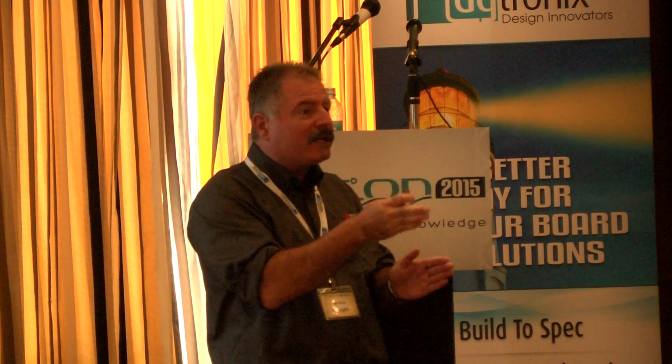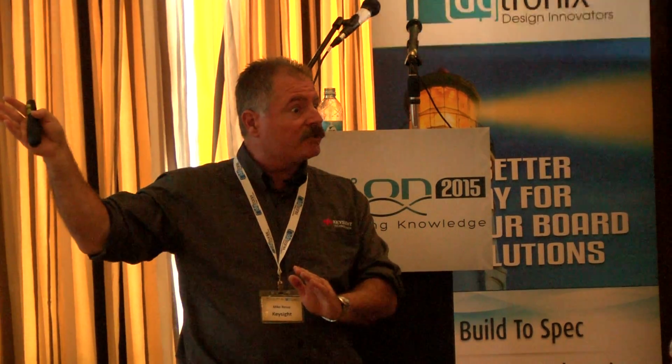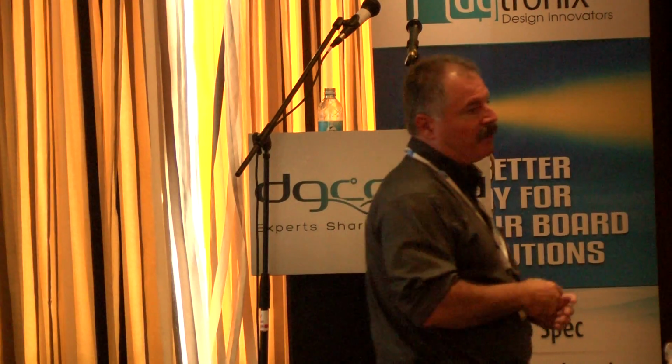A TDR doesn't have as much flexibility, so you're going to live with an initial impedance discontinuity at the very beginning of your device under test, or in this case, your fixture. So if you launch a 35 picosecond rise time, 200 millivolt TDR step into one of these channels, and it's differential 70 ohms, you're going to lose a lot of energy, and at the end of the channel, depending upon how long it is and how lossy the material is, you're going to have maybe very small signal that may be difficult to pull out of the noise because of the wide bandwidth TDR receiver. That's a generalized answer, but that's what will happen.